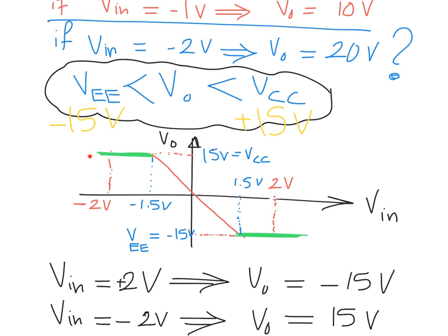And this is called the case of the saturation of the operational amplifier. Here is the linear operation, and here is the saturation. While you are designing any circuit in the future, make sure you're still operating within the linear region of this op-amp.